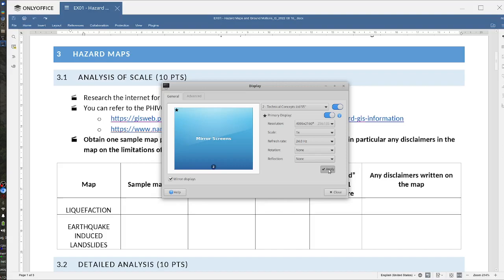So these are the two equations that we can use when converting from surface magnitude to moment magnitude. We have two equations because it depends on the size of the earthquake. For small earthquakes between 6.1 to 3, we can use the first equation. For large ones between 8.2 to 6.2, we can use this one. For example, we have an example here. Convert the following earthquake magnitudes, 5.0 and 8.1. And we have this solution here.